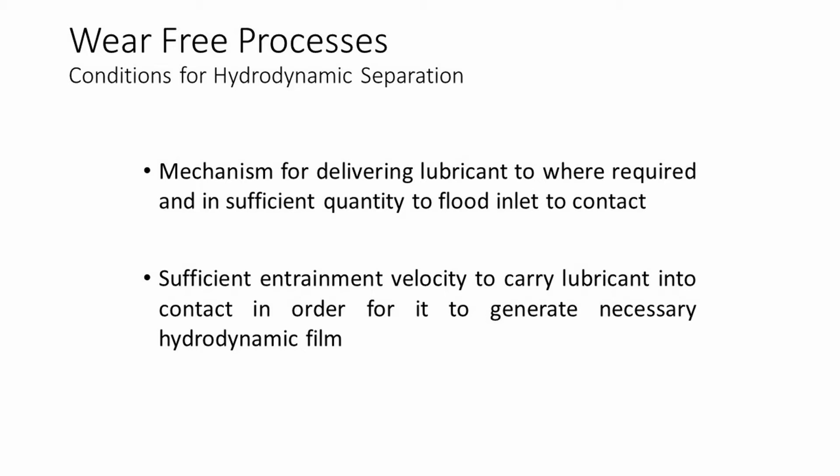Secondly, there must be sufficient entrainment velocity to carry the lubricant into the contact in order for it to generate the necessary hydrodynamic film. This latter condition, except in the case of externally pressurized bearings, requires the contact surfaces to be in motion with at least one surface moving from the direction of lubricant supply and at sufficient speed to generate a thick enough hydrodynamic film.